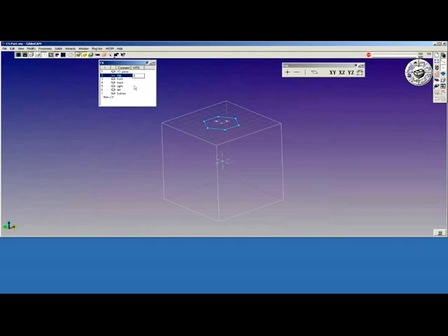If I want to mix them up, I could put another number here, make this number 6. And that would be my G59 coordinate system. In the case of having more than 6 coordinate systems, we can keep on numbering, and the post will give you the G54.1, G54.2, or whatever numbering convention your particular machine control uses. So this is just a handy method for controlling the output from the post. All right, let's close the CS dialog and go back to the top CS.